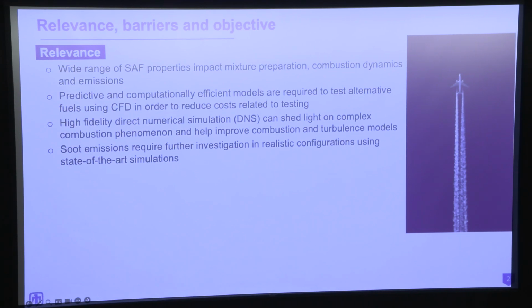Another important aspect is that soot emissions from aircraft need further investigation when you have different SAF fuels for their propensity to form soot, because the particles that exit the aircraft and their size distributions and morphologies determine how ice crystals are nucleated downstream and form contrails that add to the radiative forcing of our climate.